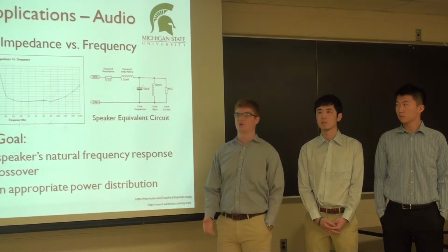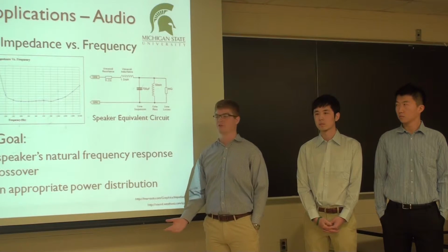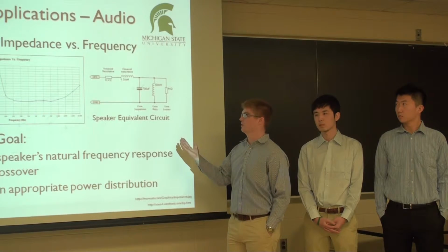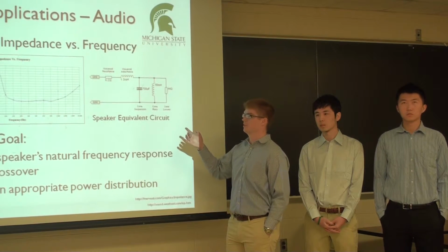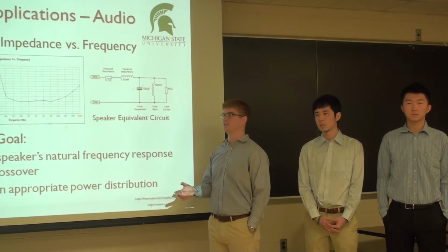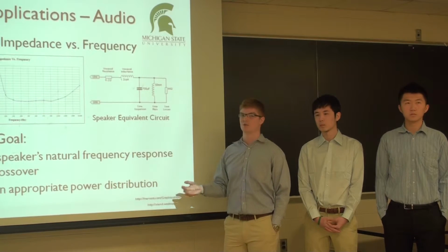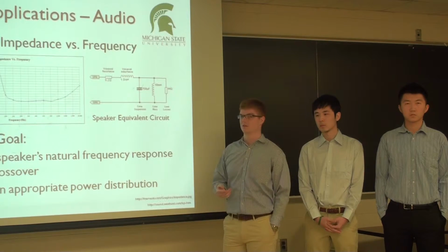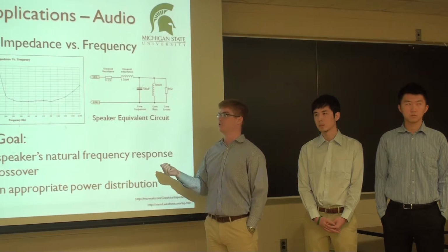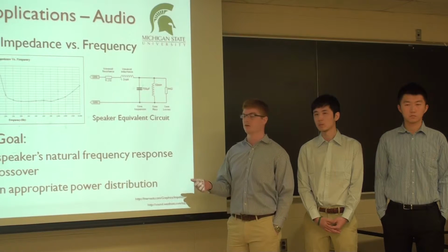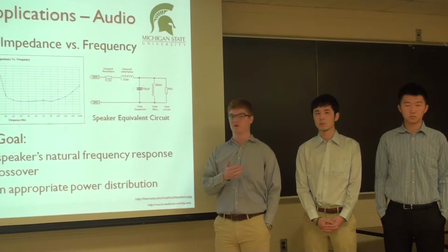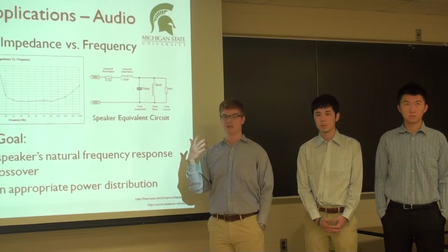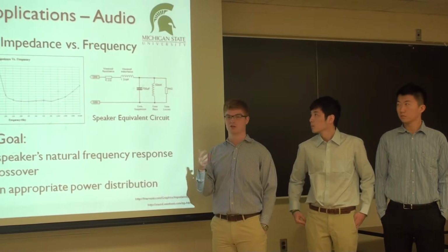So if you're using a program like TINA TI or some other simulation package, you can measure the actual characteristic values of your inductance or your non-ideal capacitance within your speaker to then help you design your crossover. So the ultimate goal is to match your crossover with the natural frequency response of your speaker and also maintain appropriate power distribution through each of the 3 speakers so that you have an even representation of your music across the entire audio band.